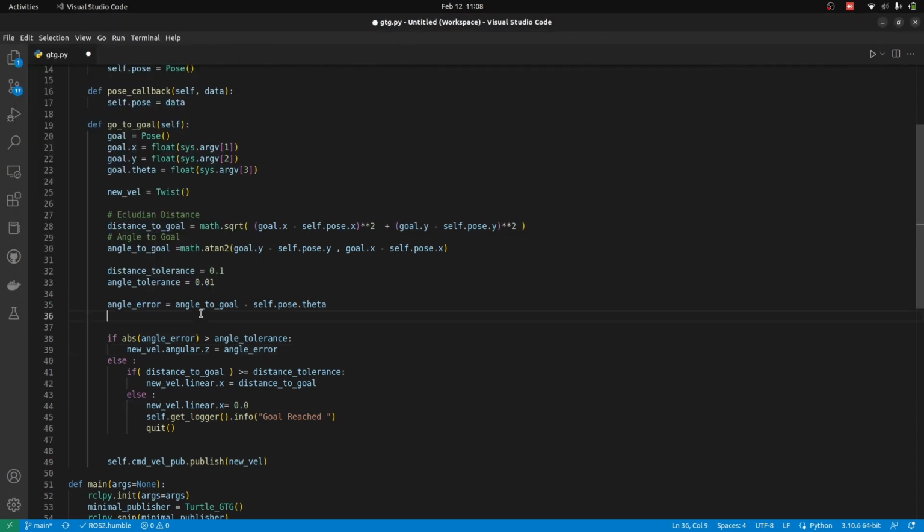What I'm going to do is to add a proportional controller, which is from control systems, and that is mainly known to be KP. So I'm going to say KP value is 1.2. It's a constant that you fine tune according to your application. I can multiply that proportional constant directly to the velocities, and we can take a look into the behavior of the robot.